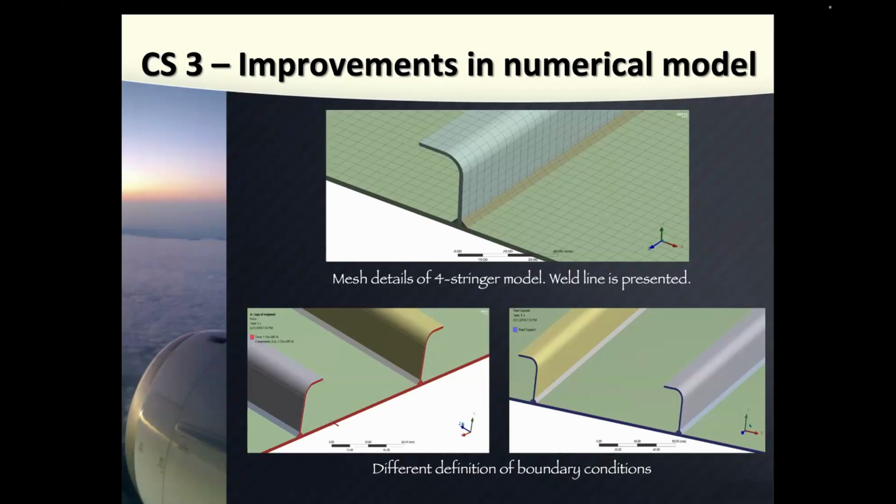So then, because I cannot repeat this experiment, I did a numerical experiment. I made a model and then changed the values of the force as it was in the experiment, from this length of the crack to this length of the crack. I changed the values of input force and calculated different delta K from them. Then when I used my results and calculated my own coefficients C and M, I got an almost perfect fit.